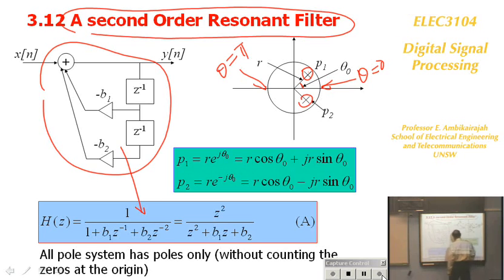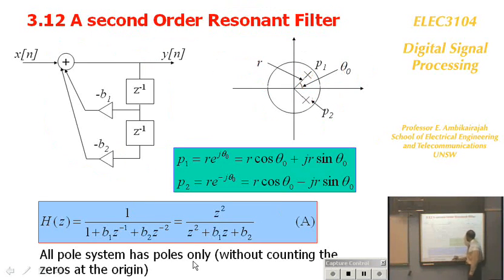And if you simplify, that is your transfer function of that system. Let's write from the pole zero position, this only pole, write the transfer function for that. Which is easy because all we need to do here is find out if this is r, this is cos theta, find out that value.